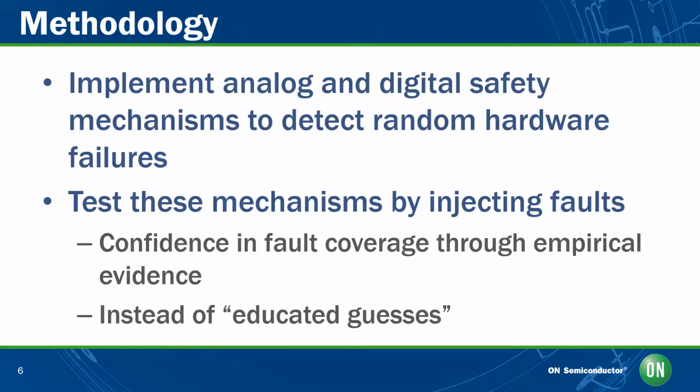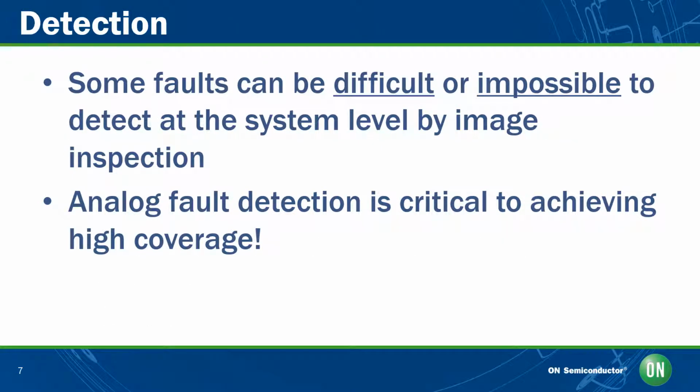Many image sensors claim high diagnostic coverage, but place a significant computational burden on the processors in the system to perform extensive checking and analysis of test data and results. Unfortunately, there are many faults that cannot be detected at the system level regardless of the amount of computational resources available. That is, some faults can only be detected inside the image sensor circuits.